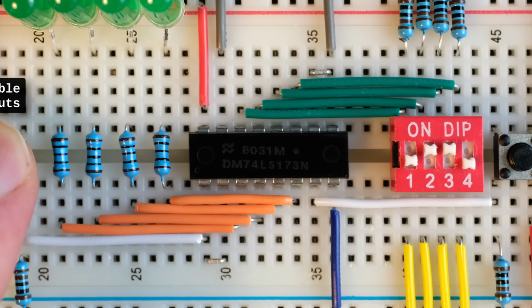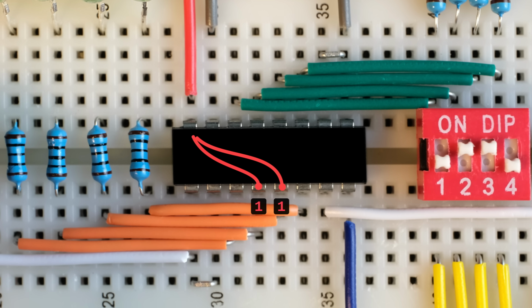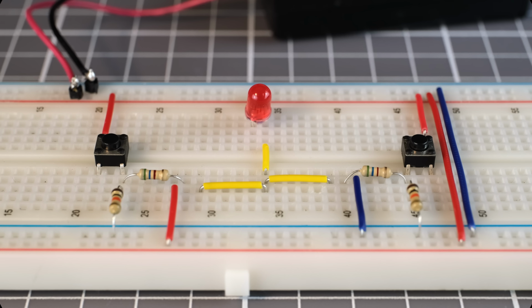Inside of the chip, all the outputs which previously were connected to either power or ground become essentially disconnected instead. This third possible state, neither 1 nor 0, goes by different names such as floating or high impedance or tri-stated, but the point is that if these outputs were connected to a bus, they would no longer be having any effect on it, and so some other chip would now be free to put its data onto the bus instead. I'd like to take a very quick look at how this works.